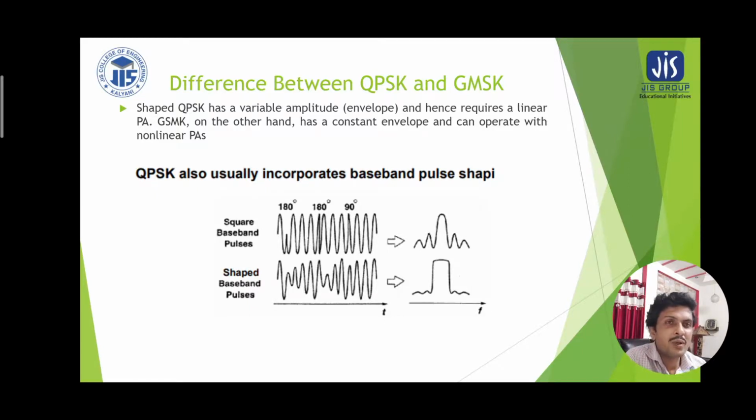That is why we have already discussed that non-offset QPSK has many disadvantages, such as the spurious fluctuations introduced due to two bit abrupt transitions, that is 00 to 11 or 01 to 10, which greatly produce side lobes, which are not only harmful for the modulated signal, but also distribute the message information in the side lobes.